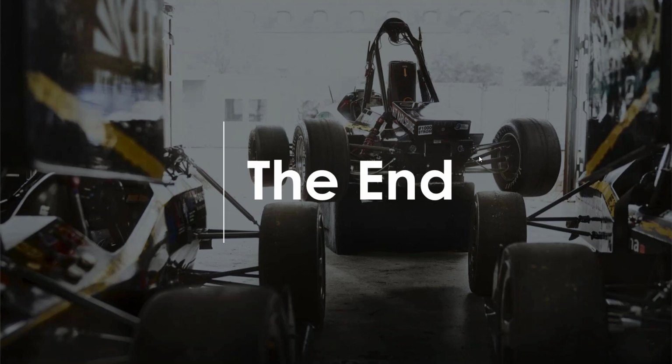Okay, so you use the tubes for the chassis. And yeah, for all the wishbones, push rods, or if you have a pull rod, we use just 1D tube elements, and the consoles we model in 3D volume elements. Okay, and at the end of the rods, you just apply regular SPC constraints, just normal single point constraints. Okay. So I hope that answers this question.